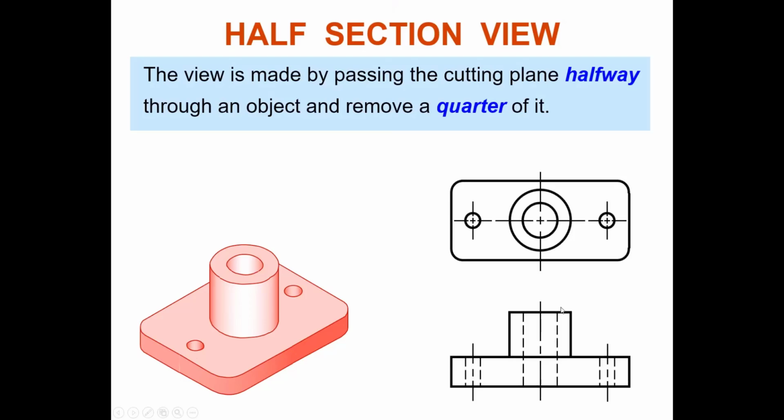Okay, some of you maybe misunderstood. Sir, do I need to make an orthographic drawing like that, make the hidden line first, then think about it, then do the section view? No. This is just for explanation. If you do a typical orthographic drawing, your front view has hidden line like this, complete. But do not do this and then only do section. No, straight away do section view.